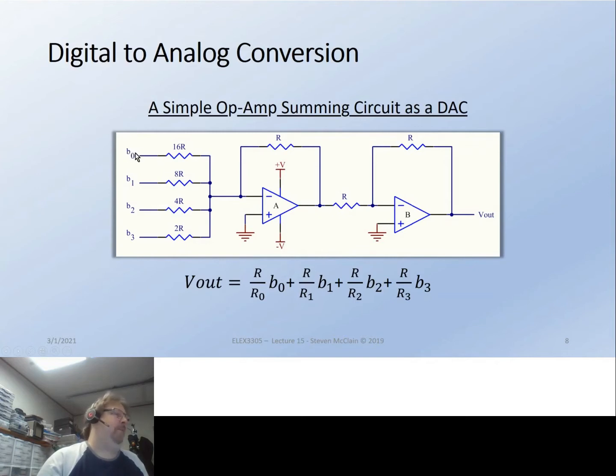And that would be our 1 bit. And then this would be the 2. So if we want to go to 2, we turn that to be a 0, that to be a 1, and all the others to be a 0, and all the other combinations for binary. You must know how to count by binary now. And effectively, depending on what combinations of zeros and ones here, it's going to give us a voltage out of here that's basically a D to A conversion. It's going to take this digital number here and convert it into a voltage there, right?